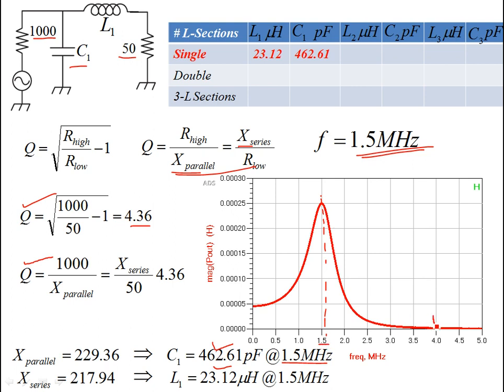You can see that there is no power being transferred at the high frequencies, and we have talked about this before. The reason is that at high frequencies, this capacitor is being shorted out, and the inductor becomes open.